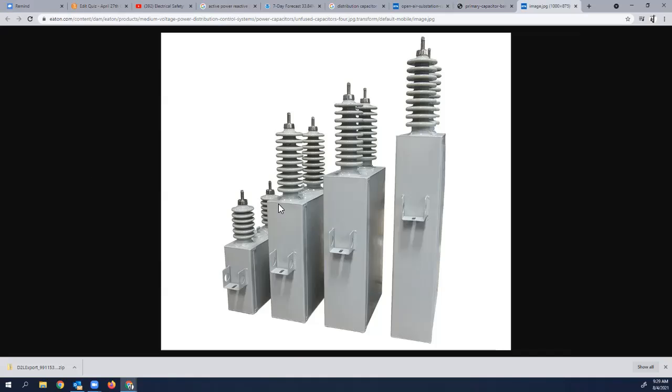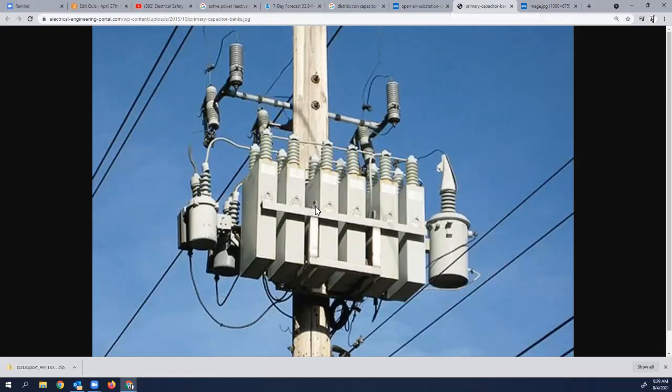For your knowledge and what you're going to need out there in the world is, they don't show it on these right here. There is a nameplate on each one of these, and it's going to show in writing 100 kVAR plus all the other pertinent information, 200 kVAR, 300 kVAR, 400 kVAR. All right. I'm not going to go to a unit and put mismatched kVARs or units inside a bank. It would not be logical to put, let's see, this is 2400, 12 200s in here. Okay, you're going to have to put 6 400s.